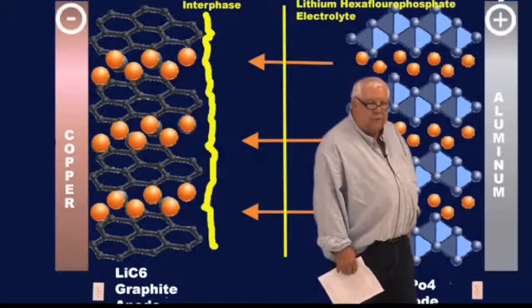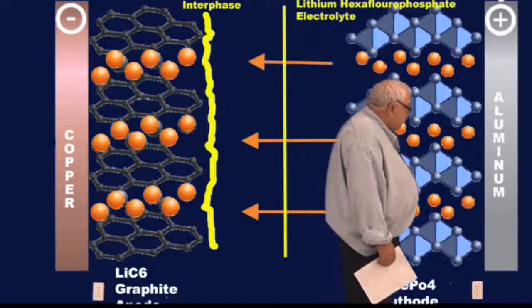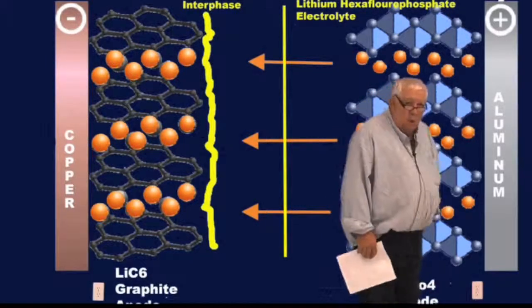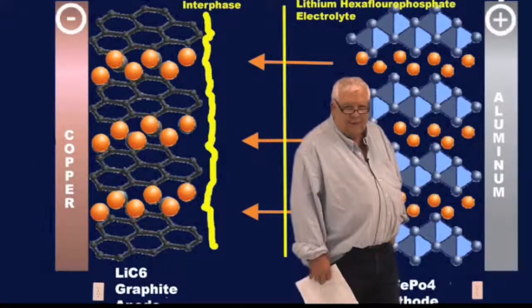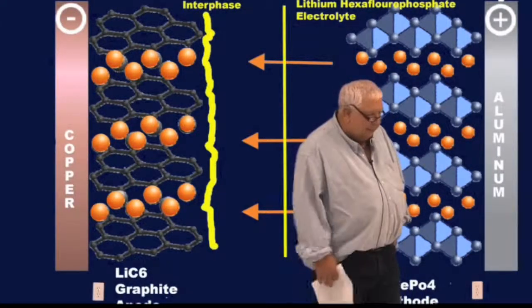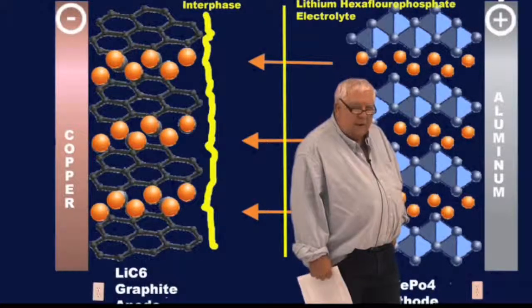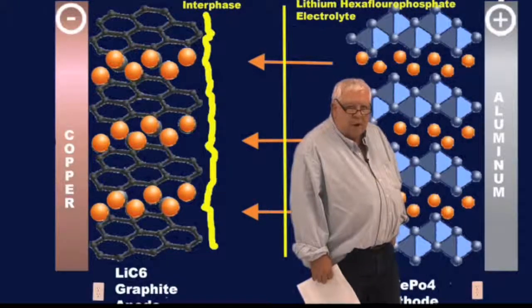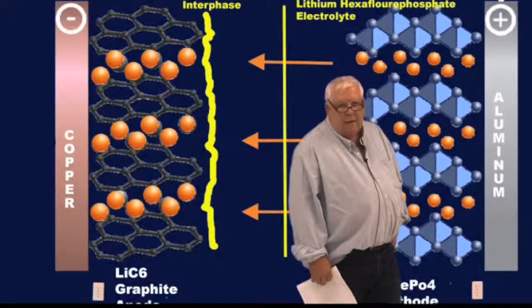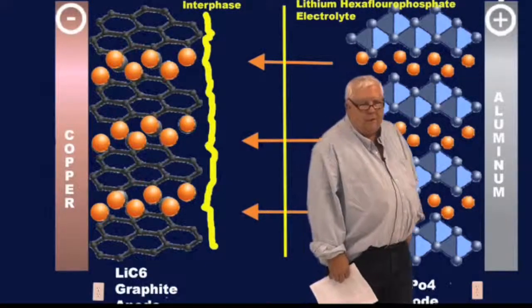And so to increase the conductivity, what we do in the cathode is mix that with carbon, which again is a good conductor along certain planes. In the anode, our battery is really based on a lithiated carbon anode, and that lithium intercalated anode is what makes the battery.